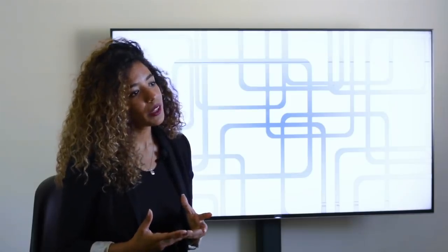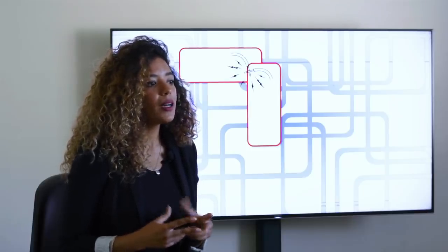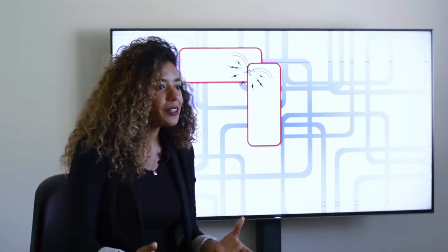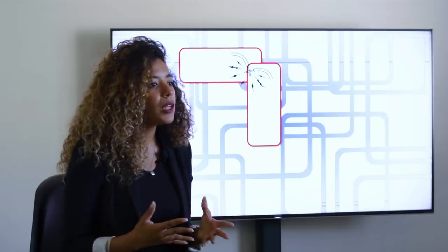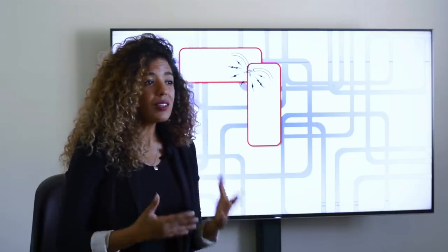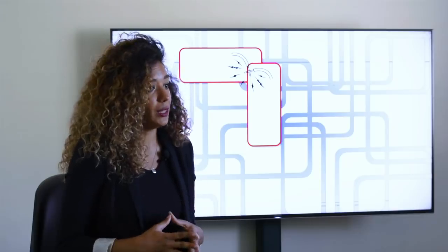Take a problem like shorted nets. A short circuit is when you have two nets that are not supposed to touch each other but are actually touching. Why is this happening? A lot of reasons. Bad routing, multiple tools, multiple designers, different databases, wrong dimensions, accidental polygon shifting, wrong assignment of a net type. Regardless of the reasons, shorted nets are a fundamental pain point in early designs.